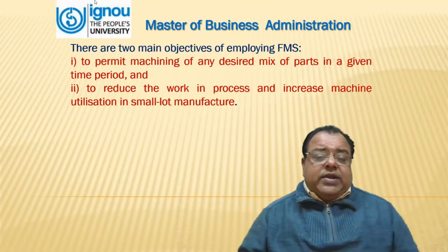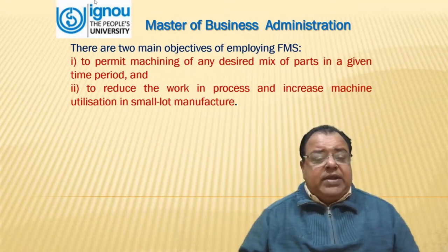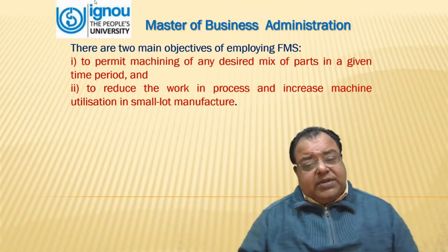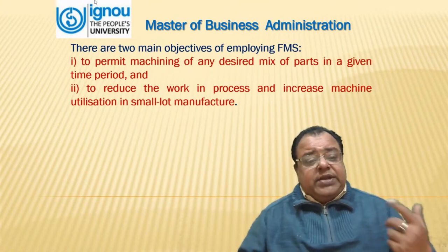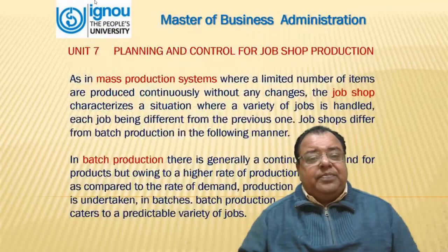There are two main objectives of employing FMS. It permits machining of any desired mix of parts in a given time period, and it reduces work in process and increases machine utilization in small lot manufacturing.